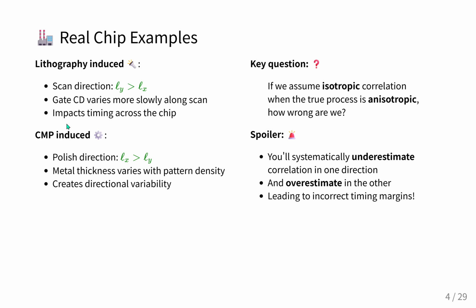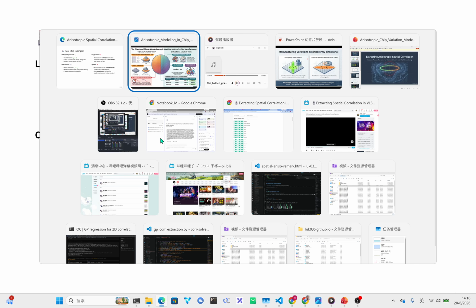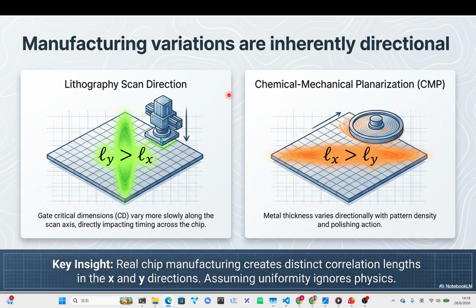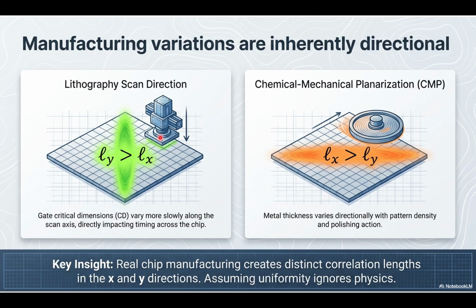Right. But let's pause there because we need to explain how a slightly stretched gate actually impacts the computer. How does a physical shape change a digital outcome? Well, it comes down to basic electrical physics, specifically resistance and capacitance. A transistor gate is basically a valve for electricity. If the lithography scanner makes that gate slightly wider or narrower along its path, you change the capacitance of that valve. Oh, wow. Yeah, it takes a tiny fraction of a nanosecond longer or shorter to fill up with electrons and switch on. Which is everything at that scale.